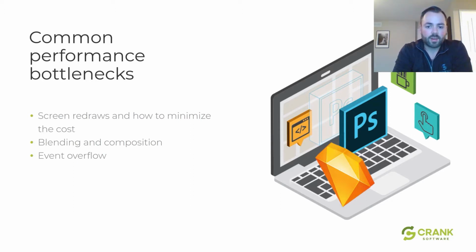So, if you think of it at that rate, if you start sending data updates every 5 milliseconds up to the UI, so perhaps speed updates from a CAN bus for automotive, or a temperature update from a sensor on a medical device. If you're sending it faster than you're drawing, then you have the potential of overflowing your queue over time.